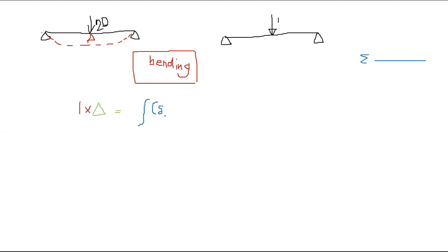So we have developed an equation. This delta M is the moment caused by this unit force, and M over EI, this M is the moment caused by the actual loading, right? So you need to interpret this. First we need to derive an expression. You can see that this point load is separating this beam into two portions. Within this part, you don't have any loading, so you can write one expression for the bending moment, and the same for this part.